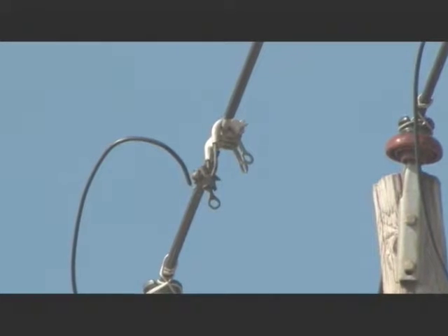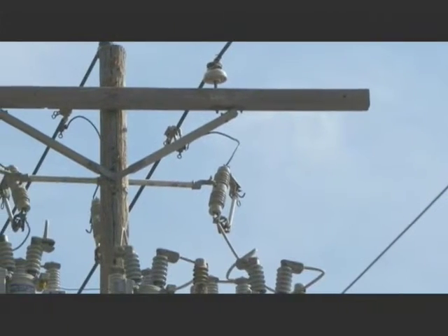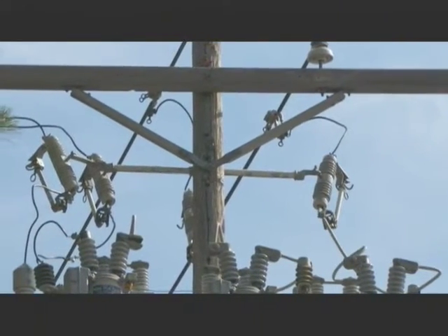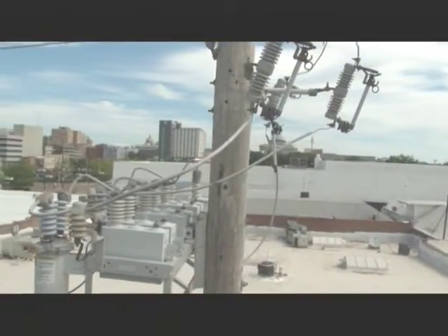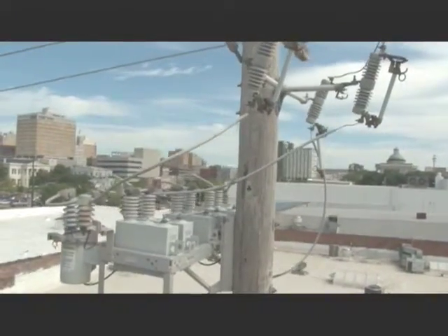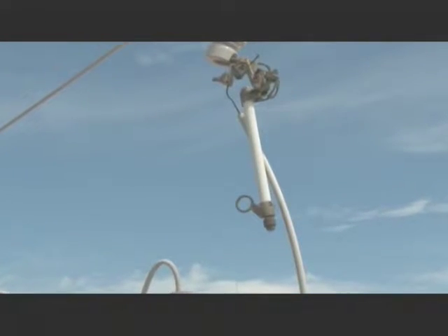As we mentioned earlier, some of the protective devices used on a capacitor bank include fused cutouts and lightning arresters. The fused cutouts installed on this capacitor bank act as both switching equipment and protective equipment. A fused cutout is installed between the feeder and the oil switch. The fuses in the cutouts function mainly to provide protection for the feeder. If a fault were to develop on one phase of the capacitor bank, the affected fuse would blow, opening the cutout and isolating the fault.